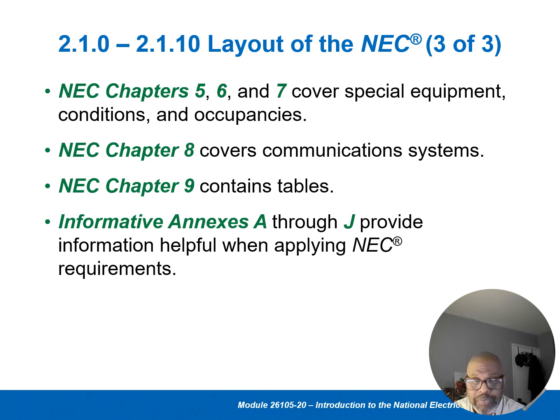When I say installed, we're talking about the conduit. For example, special equipment includes what we call explosion-proof boxes, used in locations where a spark can cause an explosion because of the environment. For example, at a BP plant where they're producing gasoline, there are petroleum products that can be flammable. If a motor is running and a spark comes from it, it could ignite something and cause an explosion or fire. So again, looking at special equipment.